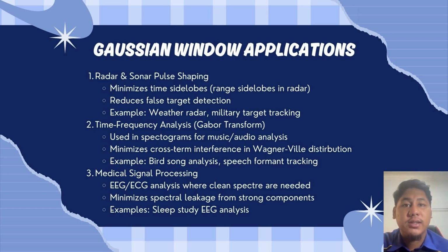Time frequency analysis in audio processing, music analysis, and speech recognition. Gaussian windows enable clean spectrograms through the Gabor transform. They minimize cross-term interference that can create artificial frequency components. Bird researchers use this to analyze bird songs. Audio engineers use it to analyze instrument harmonics.